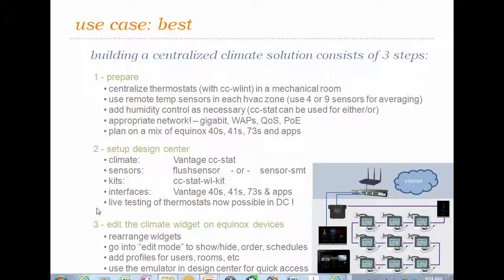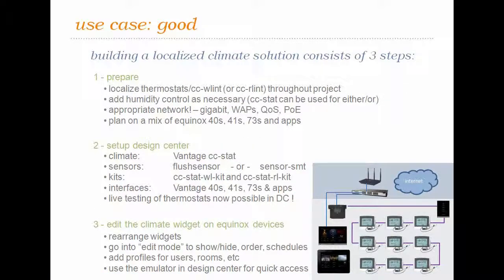You know, there may be cases as well where you have not been able to run bus. So if it's a true wireless retrofit and you're using radio product, this is a great application for that as well. Again, in these same cases, you can add humidity control as necessary. And as you recall, the CC stat can be used for either or purposes. It can be set up in the field that way. There's really no difference past this point between the best scenario and this scenario.